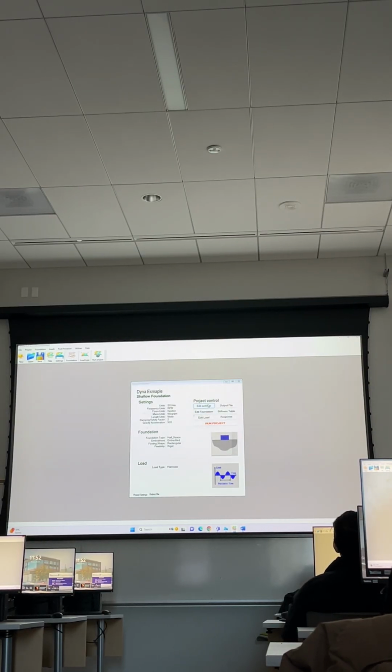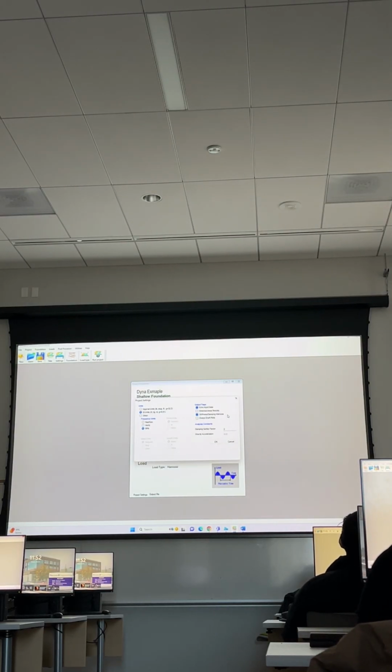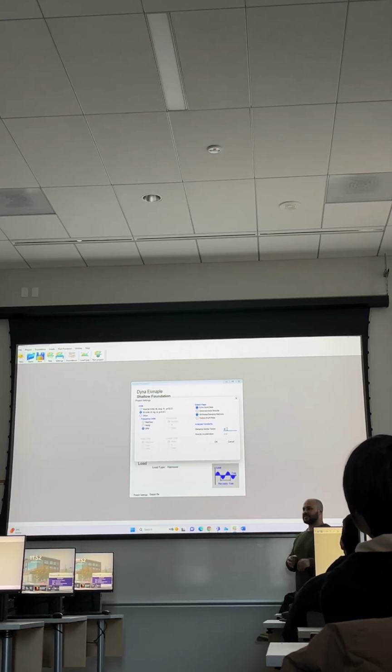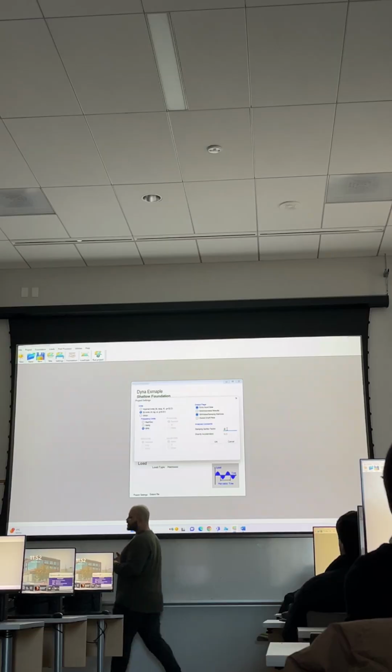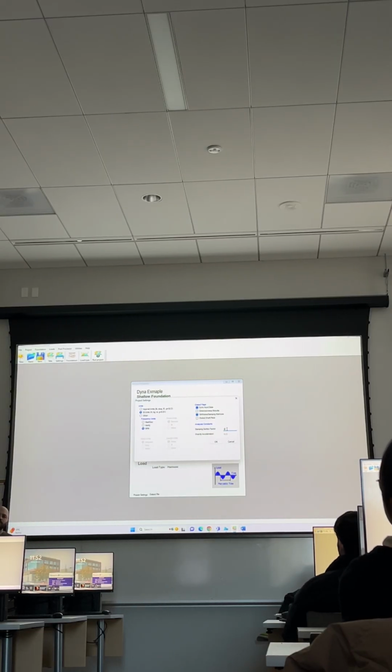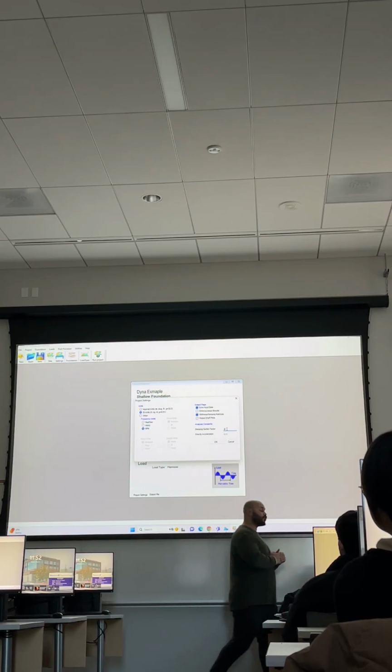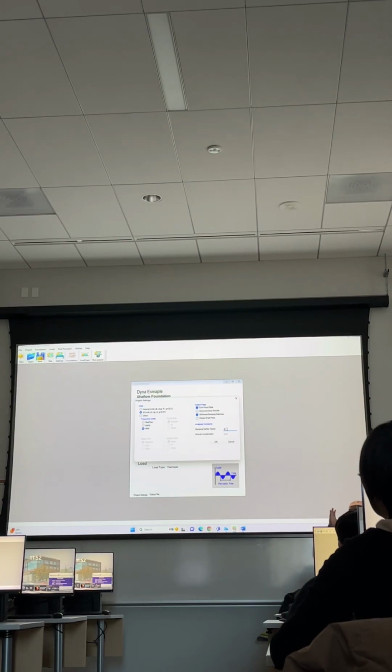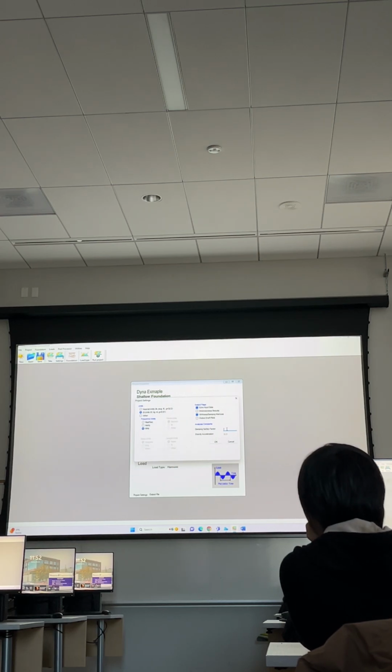Here in edit settings, for the damping safety factor, we assume that it's 2 because this is the right value, and this is the actual response. But if you just want to get exactly the natural frequency of the foundation, you can assume a higher damping safety factor, for example 10 or 12.